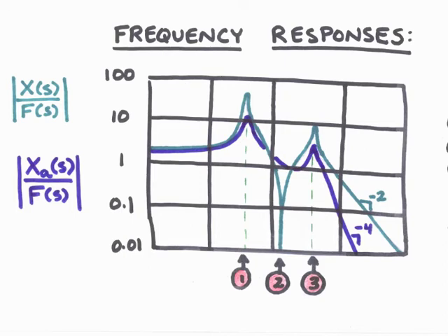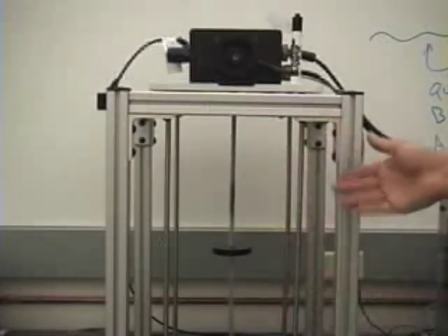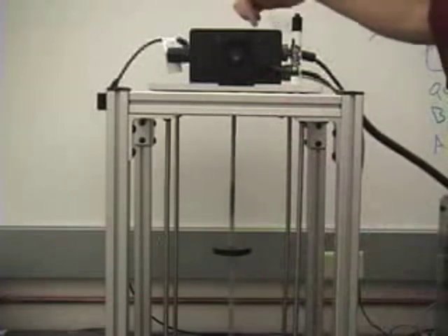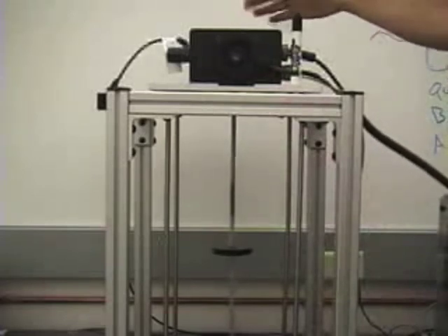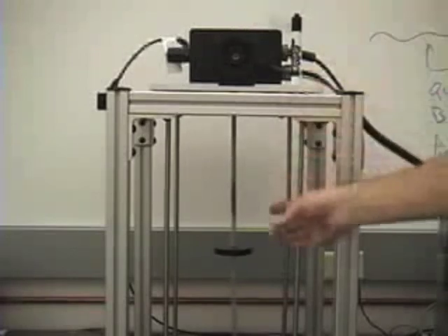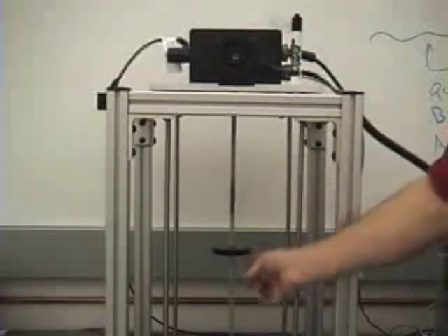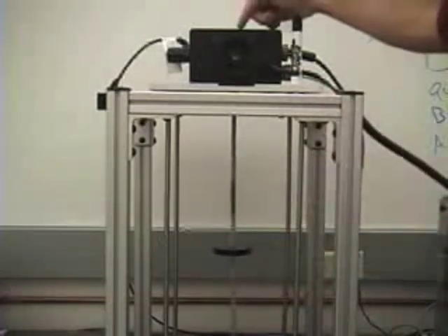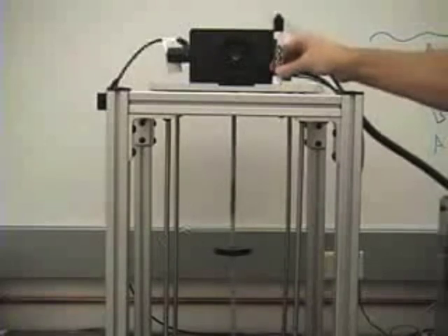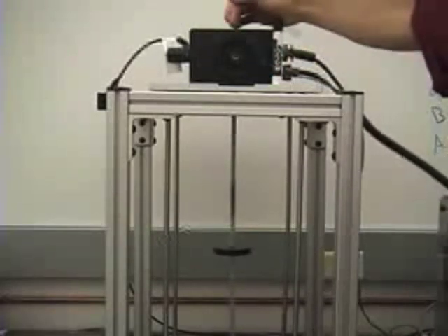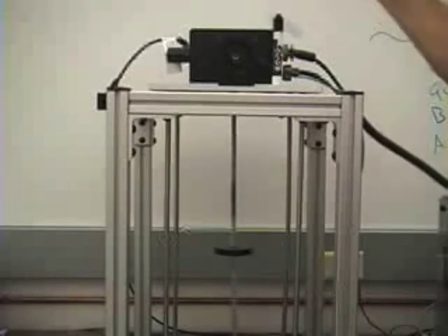Let's now look at the results from the experiment. Here we've got another single degree of freedom spring mass system where the forcing function, in this case, is an imbalanced mass which is being spun. Although we're spinning it with fairly significant force, it's not moving much because we've got a tuned spring mass damper right here. So its resonant frequency is exactly the speed that we're spinning at right now. So Bob, the maintenance man here, can stand on the top of the building with the imbalanced air conditioning unit and not experience too much vibration.